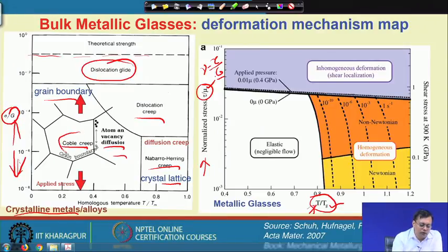So, in case of Coble creep, the atomic vacancy and diffusion proceeds through the grain boundary, and we get a Coble creep, and dislocation creep will occur when dislocation bypasses and does not move on its plane, but through the lattice itself.